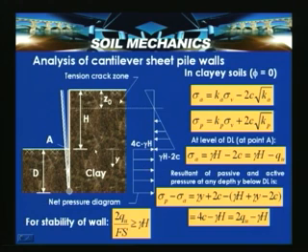If you look into this now, in case there is a tension crack or the soil is under tension, then this particular negative pressure will occur. Otherwise, if there is a surcharge equivalent to this pressure, then the pressure will start somewhere here, that it will be 0 at this point.